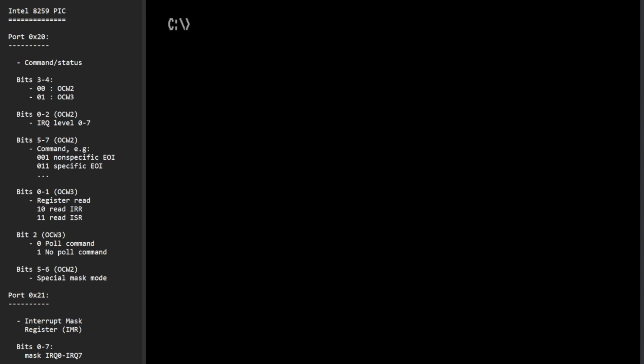Now, it won't work to use interrupts for that. If a key is pressed at a really critical point, it will mess up our cycle accurate timing and it just won't recover. So we need to be able to access the keyboard without using interrupts, and so that's the topic of today's video. Now, the first thing that we need to deal with the keyboard is to figure out when a key has been pressed.